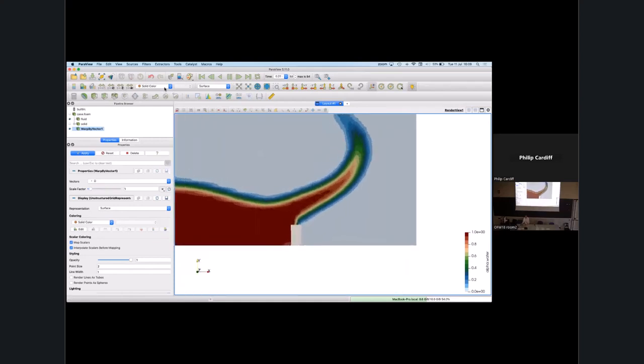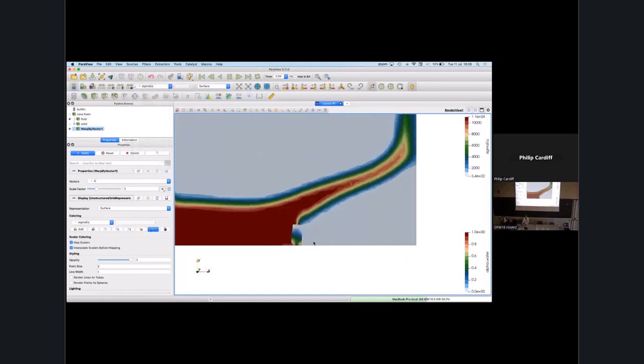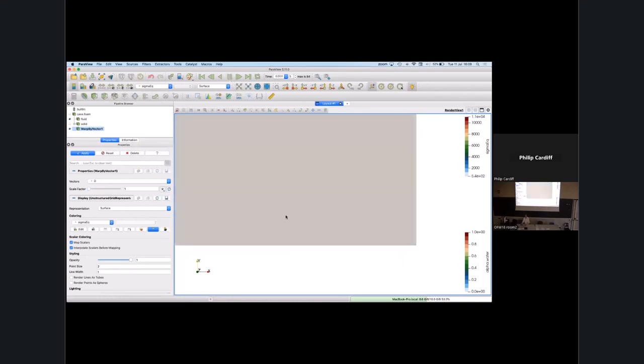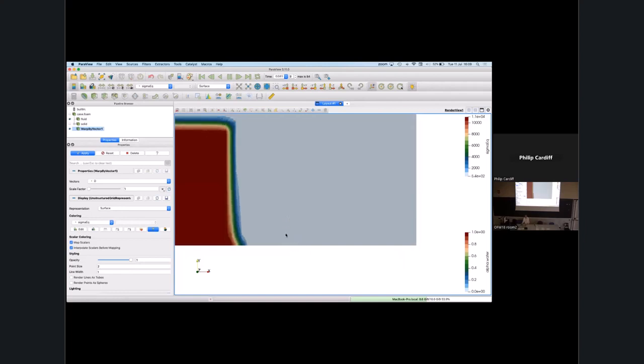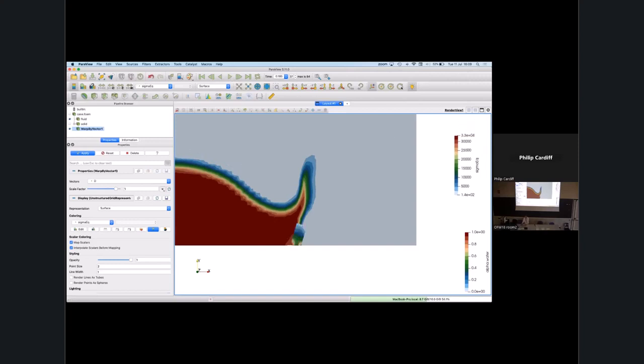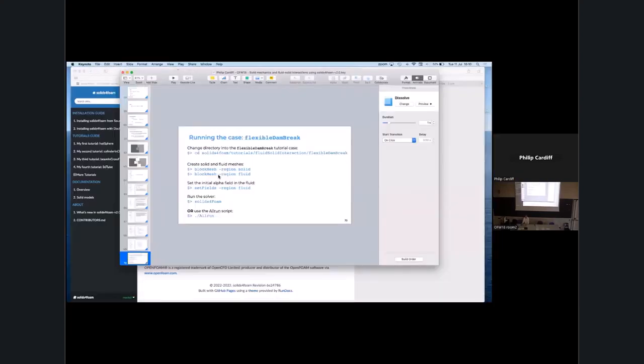Good. So we can look at things like the von Mises stress. Classic bending, the high stress will be at the outside, particularly at the fixed region. So you get a high stress at the bottom. If we change this to a plasticity model, then you might expect plasticity in those regions. If we look at the maximum stress, okay, it's very, very small, 33 kilopascals. Fine. Okay, we'll keep going.